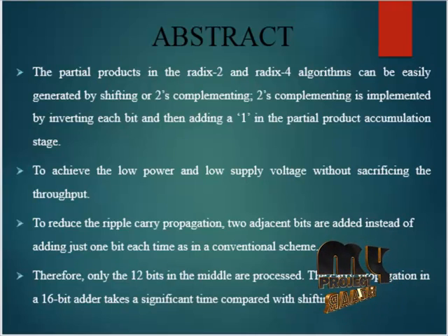With the 12-bit multiplier, the Radix-8 recoding algorithm generates 6 digits and 6 partial products are generated. After inverting, the partial products are accumulated by the Wallace tree. In this process, the approximation of the adder and the 16-bit Booth multiplier through approximate designs is proposed in the accumulation stage. Booth multipliers have been widely used for high performance multiplication and encoding.